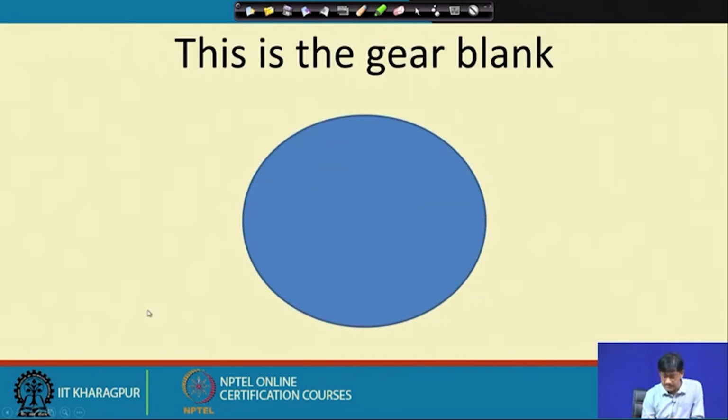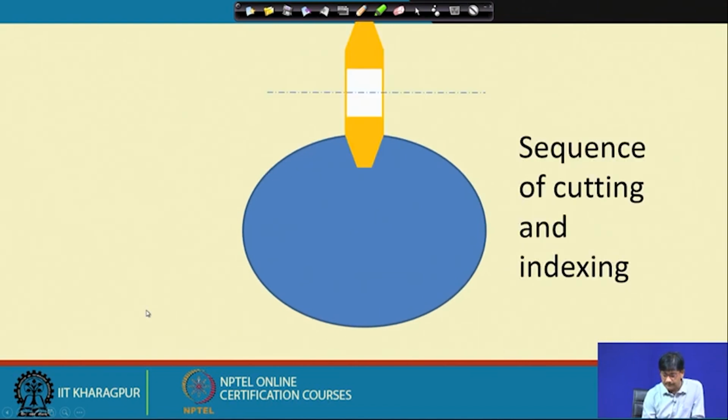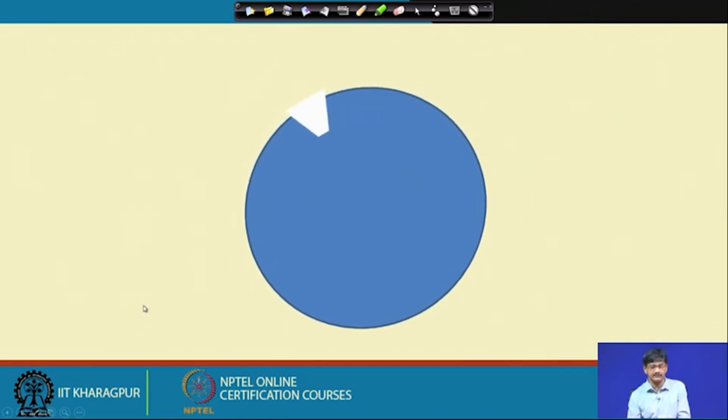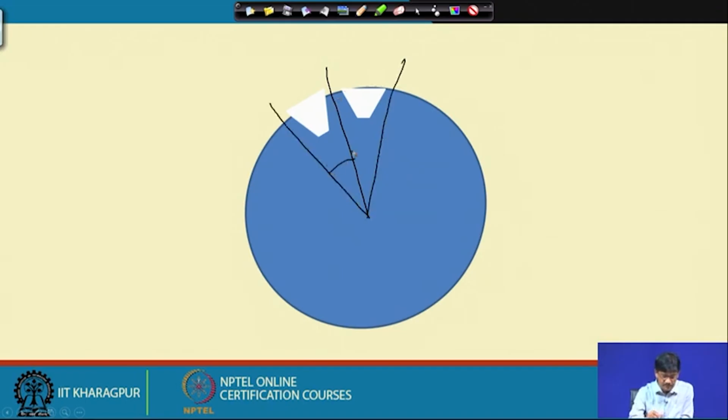So, how is this done? Now, let us see the other view. This is the cutter. It cuts the material. Then this is what you do by indexing. You shift it exactly by 1/71st of a rotation, so that a potential portion has come, the cutter again appears and removes it. Please consider the drawing because it is not very accurate. So, this is what we are doing. So, we have to make it possible to rotate by this amount every time. Every time I cut a tooth, if there are 71 teeth here, 1/71, 1/71, this rotation has to be given successively 71 times.